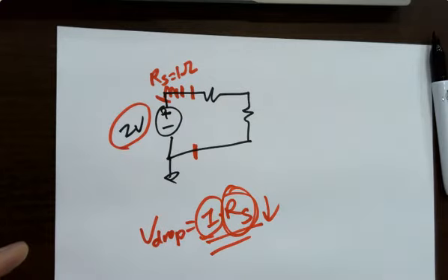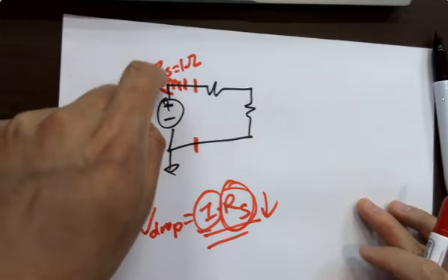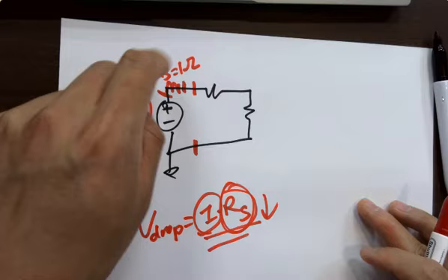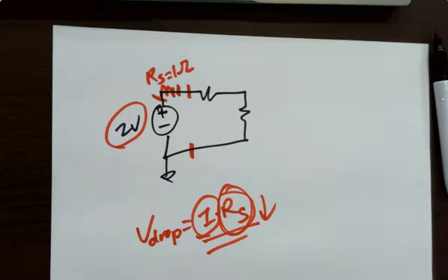It makes sense, right? You are supplying voltage, but you are dropping everything by itself, internally. You don't want to do that. You want to drop all the voltage outside, so you are supplying voltage to the outside world instead of internally. So making RS tiny will be the goal of any voltage supply, right?